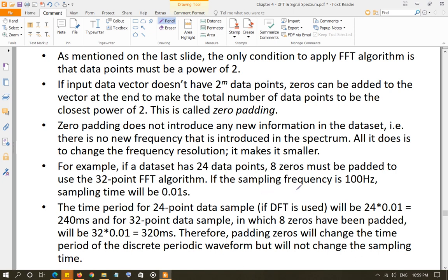You're not going to go and add zeros there. All you need to do is FFT. Let's say x has 100 points, but you can just say x and then use 128 points. It is going to check the length of x, and if it is 100, it's just going to insert 28 zeros and then give you the discrete Fourier transform using the fast Fourier transform algorithm. That's all you have to do.